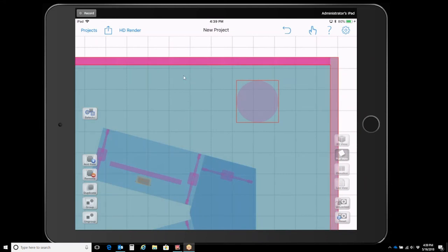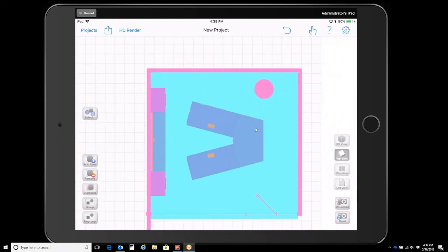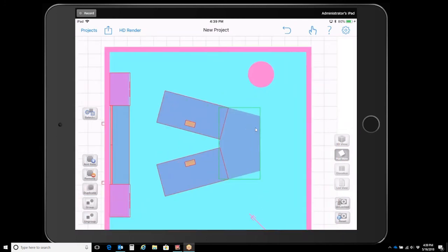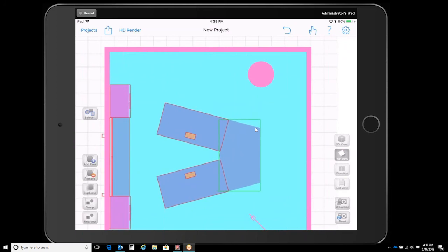Now, the only thing is I find that this point here is going to be a little bit too tight for anybody to walk in. It's roughly 2 feet. So let's make sure that, again, my client has at least 3 feet of walking space between furniture items and any architectural item, such as the wall column. Okay.